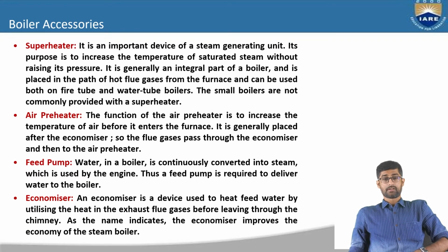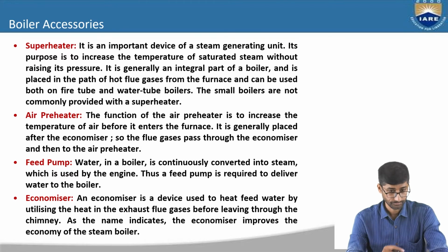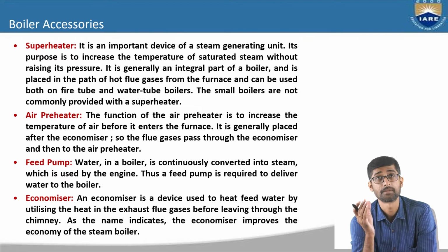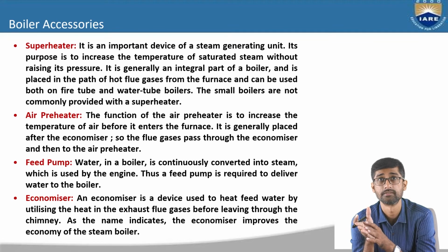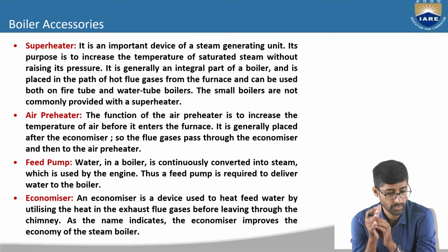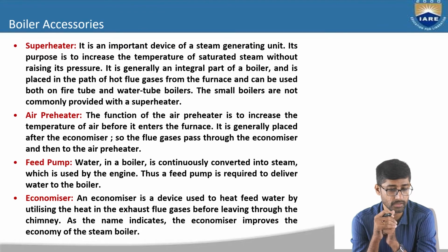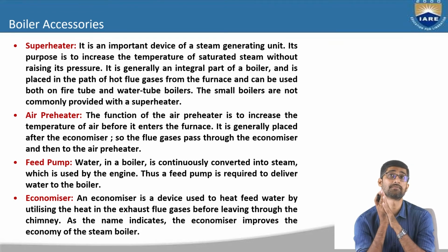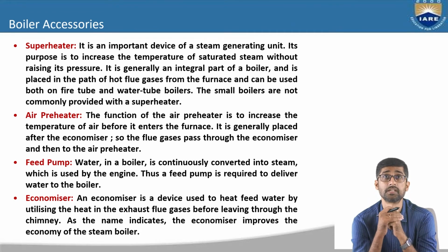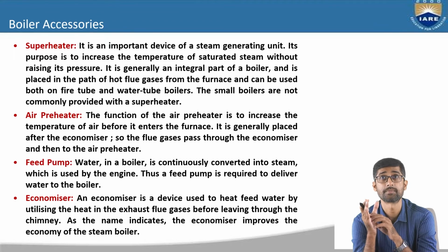Next is boiler accessories. As I have told, the boiler accessories are the most integral part of the boilers. Without boiler accessories, the boiler cannot work. So these are the four most important boiler accessories. First one is the superheater. So what is a superheater? Its purpose is to increase the temperature of the saturated steam without raising its pressure.